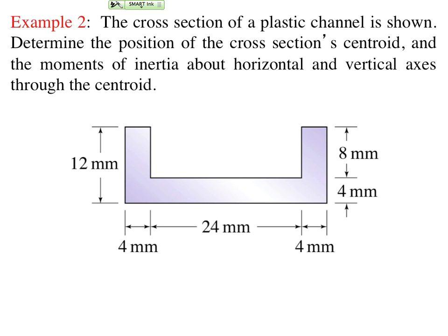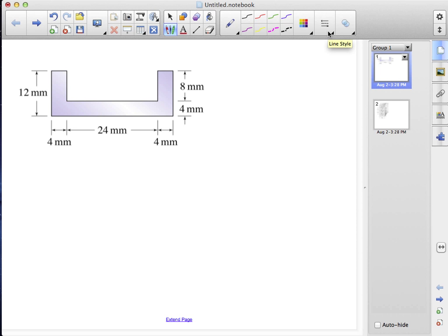This U-shaped cross-section is symmetric about a vertical axis bisecting its base, so we know that for a cross-section positioned at the center of the base, x bar is 0. We don't yet know the value of y bar in this coordinate system. We want to first find the centroid, then find the area moments of the cross-section about a coordinate system positioned at the shape's centroid. In problems like this, we need to pick a coordinate system somewhere to start with.